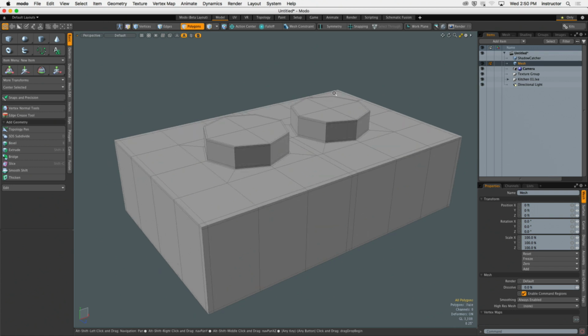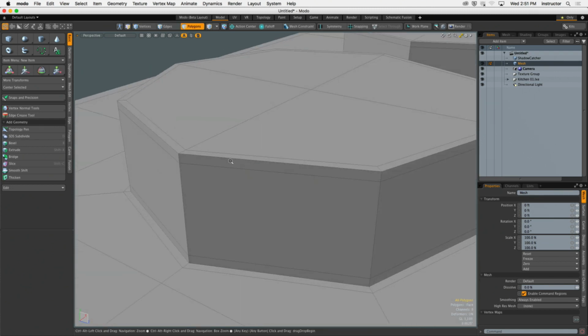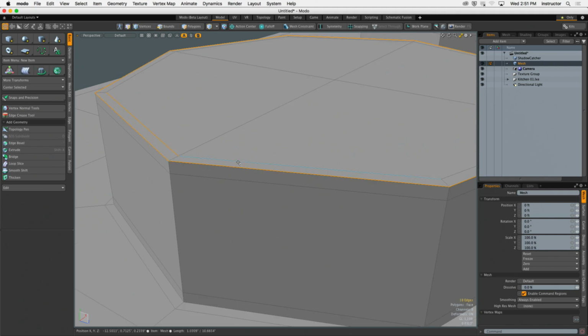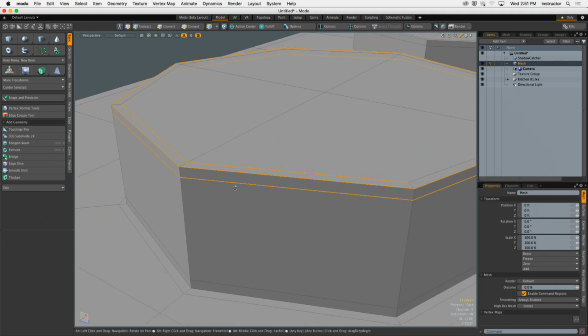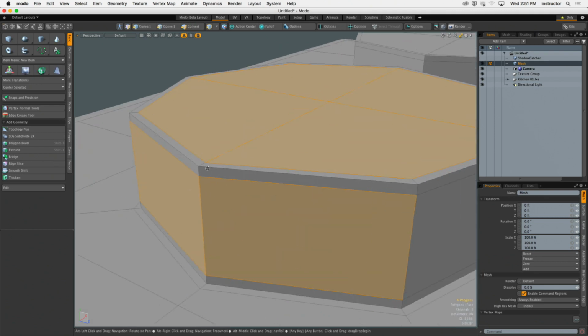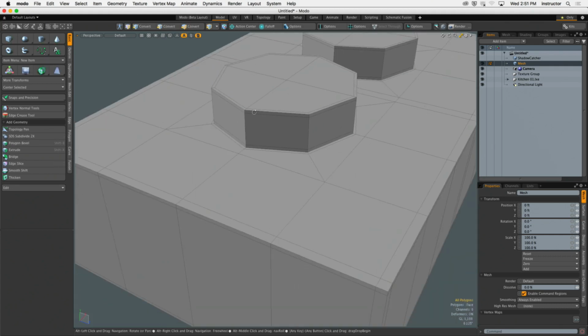Because this is the raw shape itself, okay, the unsubdivided polygons. Of course, from our earlier examination of sub-Ds, if this is the original edge, we have to have one edge above and another edge loop below. And I've continued that pattern at each of the transitions between the different surfaces, okay? So I have a surface plane here that transitions over the top, so I need to have some edge loops in here to shore up the algorithm and to reduce the influence of the smoothing.